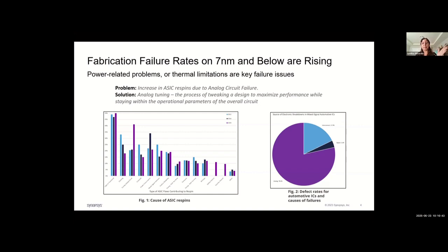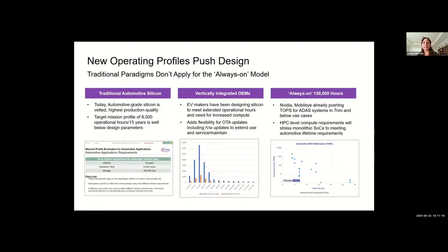On the left side, we talked about the extrinsic defects and the manufacturing variability causing higher infant mortality and a higher incidence of early life failures. But the right side of the bathtub curve is now also getting stressed, because we now see early failures from an intrinsic reliability standpoint, and those defect rates rise, where we see more of that natural wear out happening early on as we continue to stress our systems, given the high performance KPI that we need to meet.